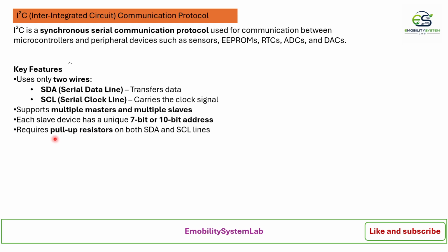And apart from that, in I2C we require pull-up resistors on both the SDA and SCL lines. So don't forget about the pull-up resistors in I2C.